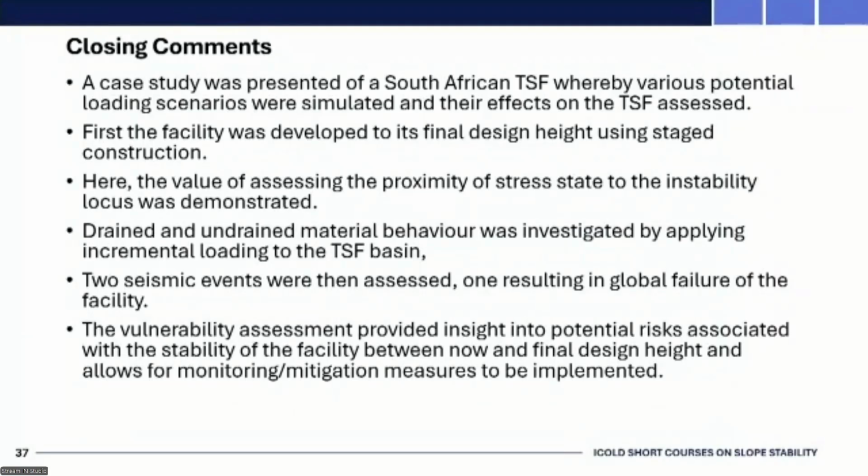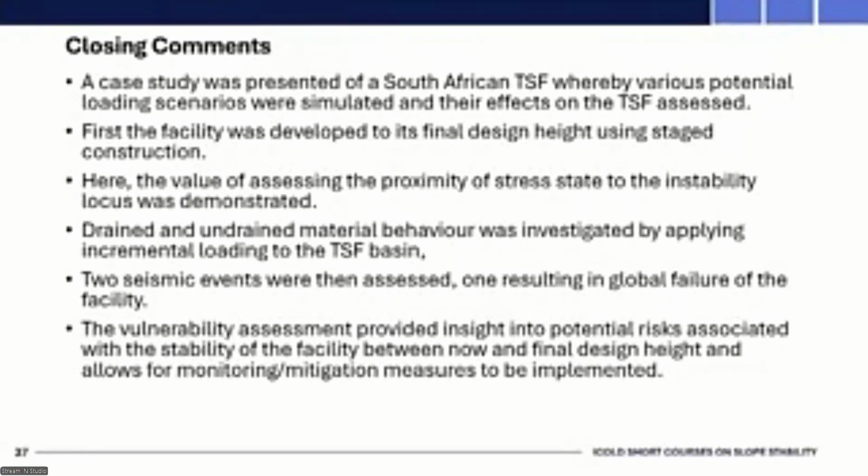A demonstration of drained versus undrained material behavior was investigated by applying an incremental load to the basin, and then 2 seismic events were assessed, one resulting in global failure of the facility. The vulnerability assessment provided insight into potential risks associated with the stability of the facility between now and final design height, and it allows for monitoring and mitigation to be implemented.